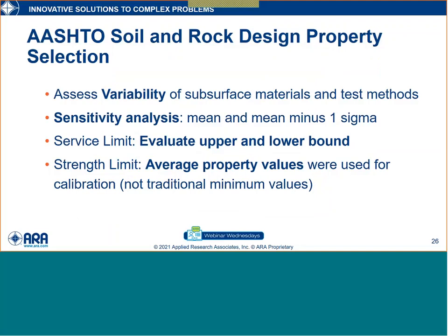So there is guidance in AASHTO on how to select. AASHTO is the American Association of State Highway and Transportation Officials. The section I'm referencing is section 10.4 of the bridge design specification, and it suggests a reasonable approach to the evaluation during the design phase of the project on how to select the geomaterial parameters.